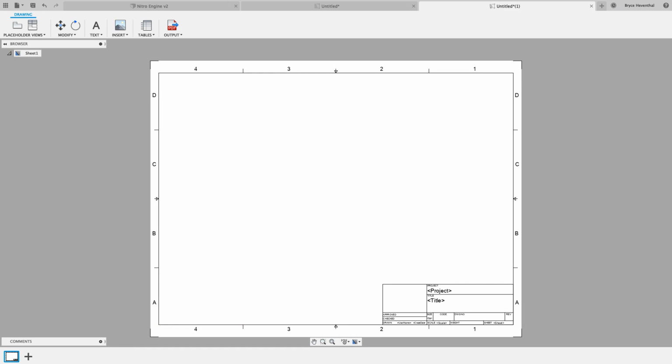All right, so what we're going to be doing now is basically starting with our title block. And the title block is always the best way to start, and then we'll start to move on to making smart templates. So our title block, let's jump right back in and show you how to do that. So we're just in a blank document. If I needed to change the sheet size or sheet scale, we could come to the sheet size and change it to a B, an A, flip it from landscape to portrait. Let's leave it at the C.